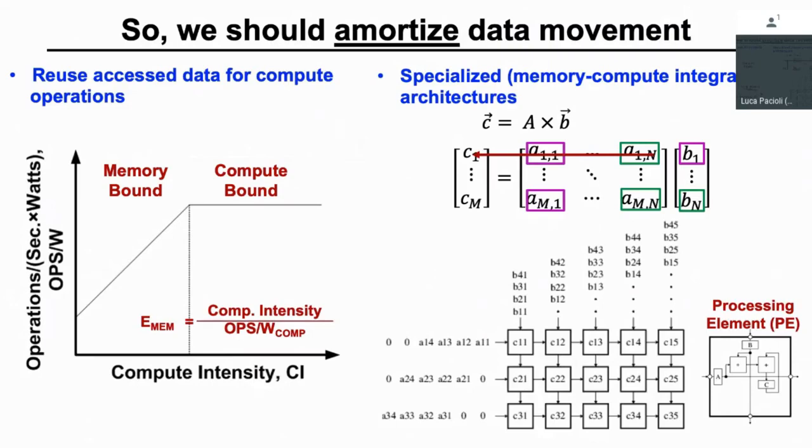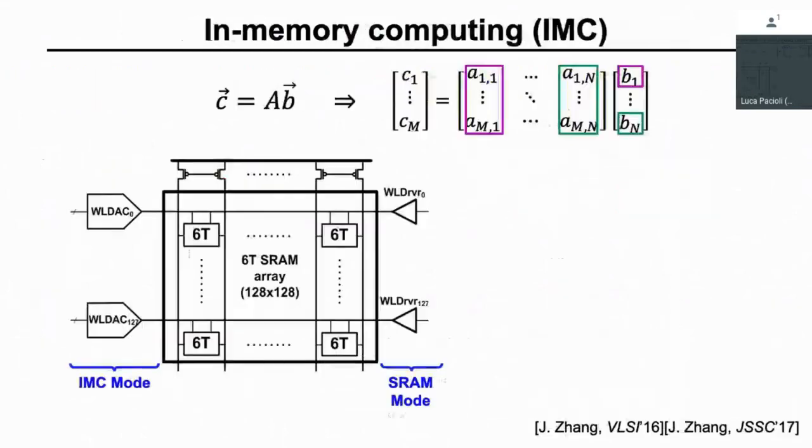And what, in fact, this allows me to do is, there's not just a reuse opportunity across this column. There's also this output partial product that gets reused. And so what we do in this two-dimensional array is create a structure for our hardware that's actually aligned to the data flow that we have in a 2D matrix. And so in fact, you're not just amortizing this memory accessing, you're also amortizing the data flow that you might have here. So there's a lot of opportunities to take advantage of this.